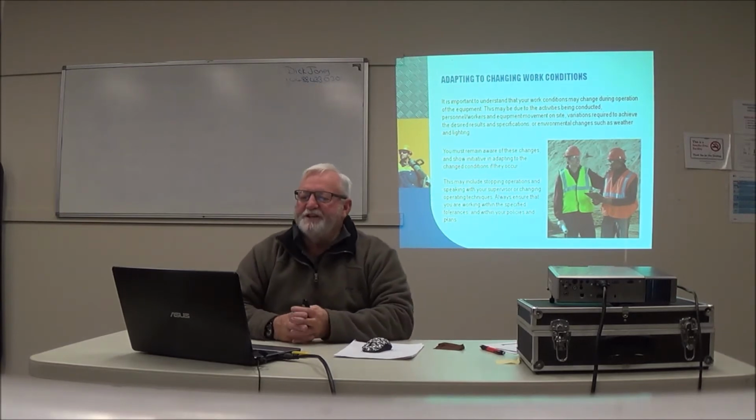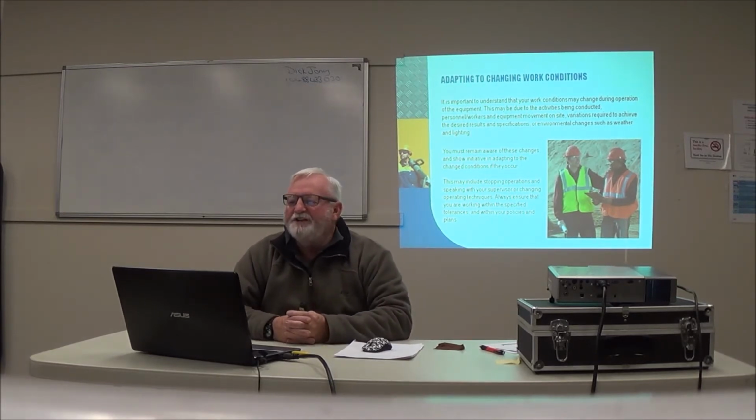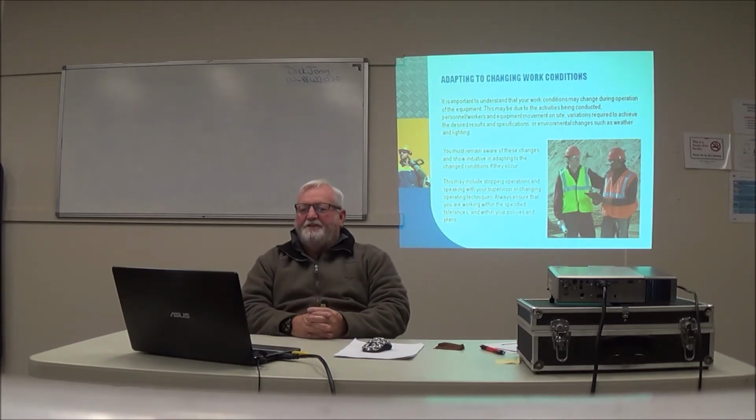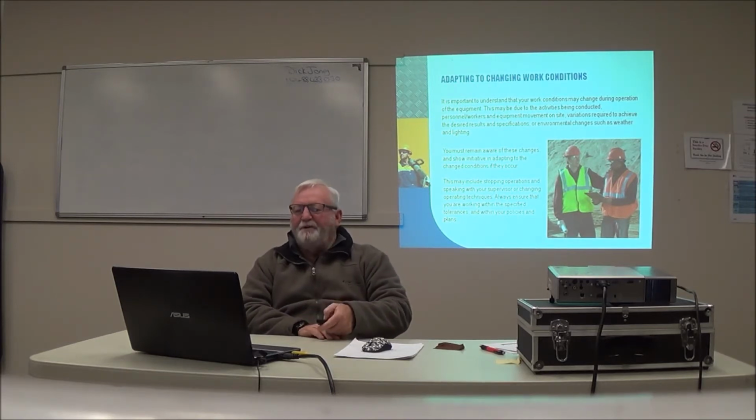Adapting to changing work conditions. It is important to understand that your work conditions may change during operation of the equipment. This may be due to other activities being conducted, personnel, workers and equipment involved on the site, variations required to achieve the desired results and specifications, or environmental changes such as weather and or lighting. You must remain aware of these changes and show initiative in adapting to the changed conditions if they occur. This may include stopping operations and speaking with your supervisor, or changing your operating techniques. Always ensure you are working within specified tolerances and within your policies and plans.